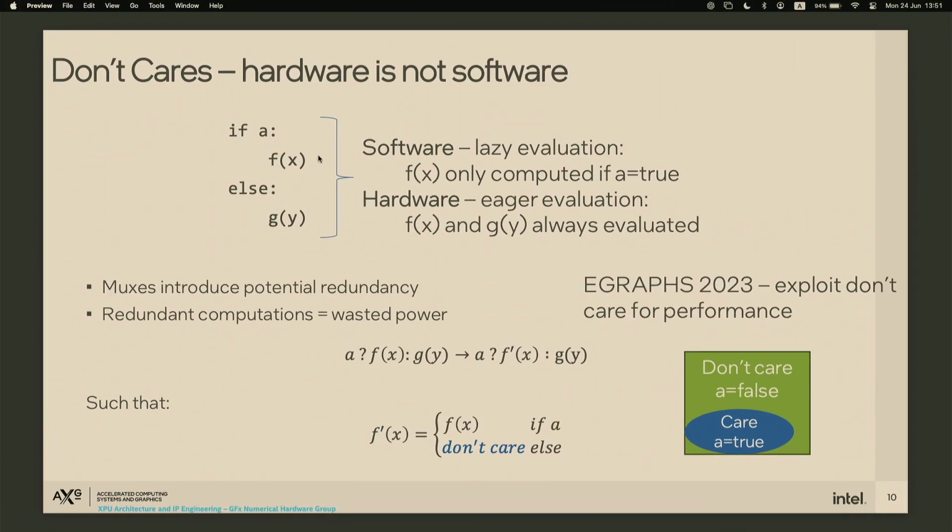And clearly, this only makes any sense if these 2 things are actually correlated. But we can also say, we've got a bunch of don't care space, basically. And hardware talks a lot about don't care space. We exploit don't care space for absolutely everything: hardware, performance optimizations, area optimizations. We don't need to handle special cases because someone in the pipeline of our floating point unit has already dealt with the NaNs and the infinities, so we know we're not going to see them. So we don't have to build a bunch of hardware to actually go and use it.